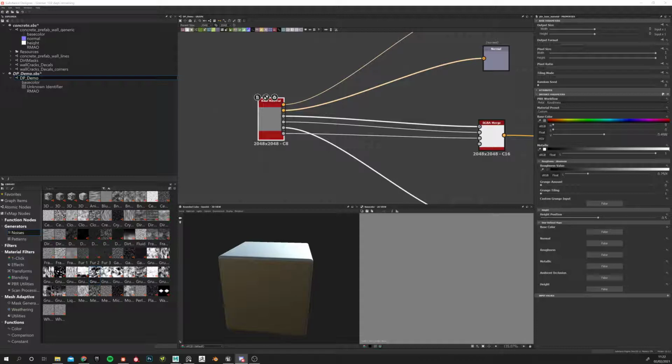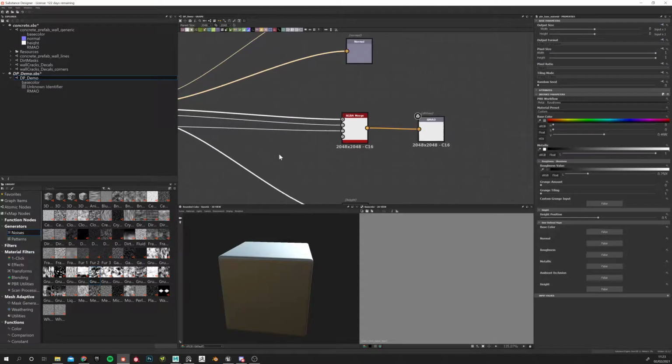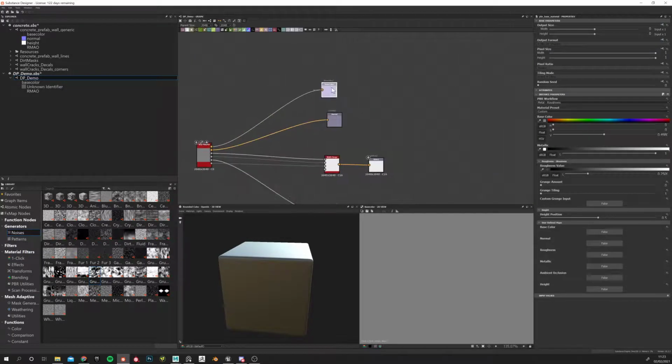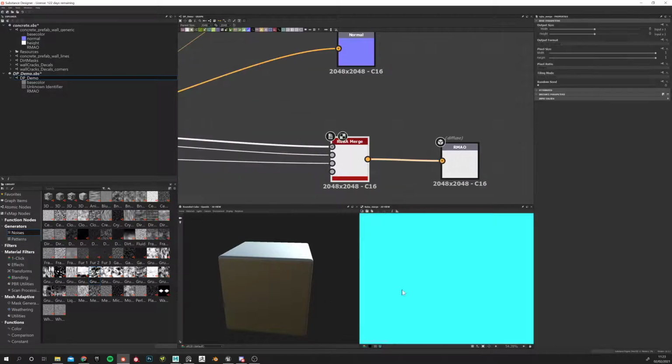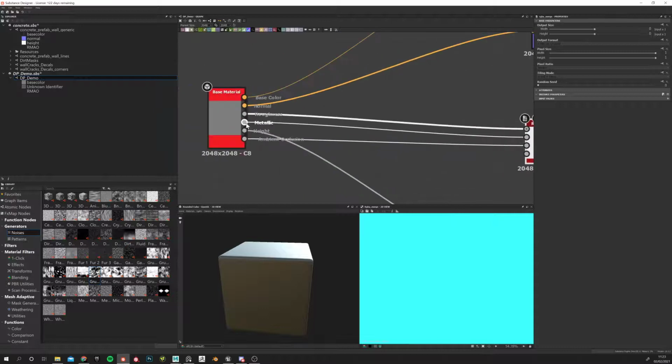Okay, this is very important, guys, because I still see on G3 and even in Masters that people are messing up the roughness map and the metallic map because they don't have a thorough understanding of this. Now I'm going to demonstrate what this looks like. At the moment we have a base color, which is 50% gray. We have the normal map, which is neutral, with no detail. Here we have RGBA, which is roughness, metallic, and ambient occlusion.